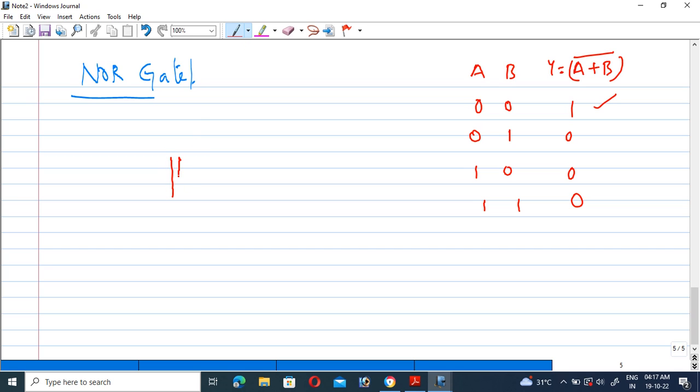So this is a depletion mode nMOS transistor, and I will represent it like this. It is connected to VDD, so the gate is also connected to the source terminal. I will treat it as the output. In this consideration, previously we connected the nMOS transistors in a series fashion. Now we connect them in the form of a parallel. Okay.